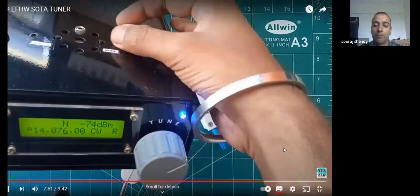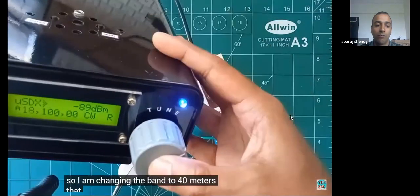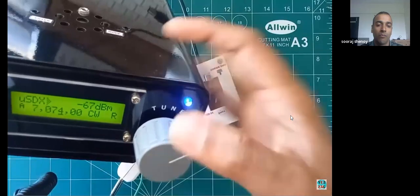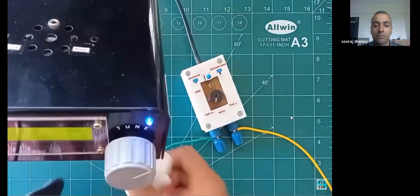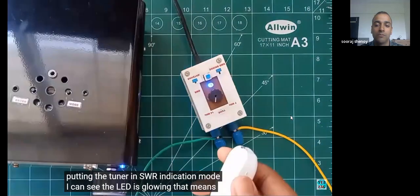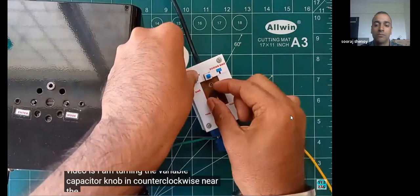Now let's check the same for the 40 meter band. So I'm changing the band to 40 meters, that is 7 MHz in CW mode. Putting the tuner in SWR indication mode, I can see the LED is glowing, that means VSWR is high. I'm turning the variable capacitor knob counterclockwise near the 40 meter marking.